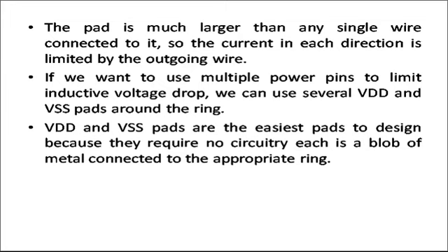The pad is much larger than any single wire connected to it, so that current in each direction is limited by the outgoing wire. If we want to use multiple power pins to limit the inductive voltage drop, which we have seen in the earlier case, that is supply and ground bounce. That's why, to reduce the supply and ground bounce, we use multiple power and ground pins. Thus we can use several VDD or VSS pads around the ring.